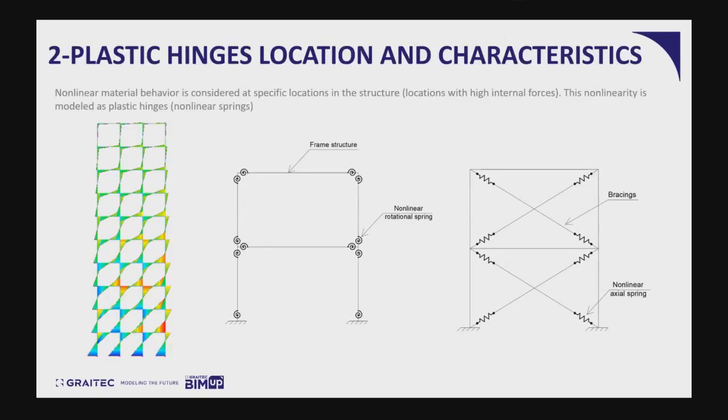Now, after defining the load pattern on the structure, we need to define where we might have nonlinear behavior in the structure. Because if we give any structural element the potential of undergoing nonlinear material deformation, this would require an enormous calculation time in the model. To be realistic, we know that nonlinear deformations will occur in the most stressed zones inside of the structure.